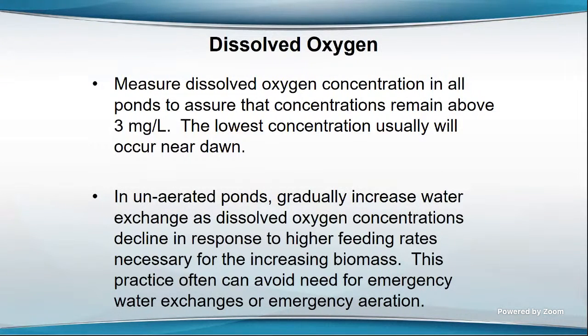I did see a study done once where they had a number of species of fish. The US EPA did it, and they concluded that when the oxygen got under about 50% of saturation, most species of fish didn't grow quite as well, but you didn't get any real big effects until it got on down, maybe to 25 to 30% of saturation.